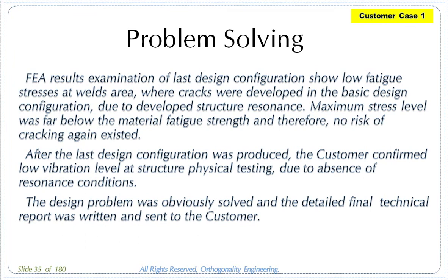Problem solving. FEA results examination of the last design configuration showed low fatigue stresses at the weld area, where cracks had developed in the basic design configuration due to structure resonance. Maximum stress level was far below the material fatigue strength and therefore, no risk of cracking again existed.